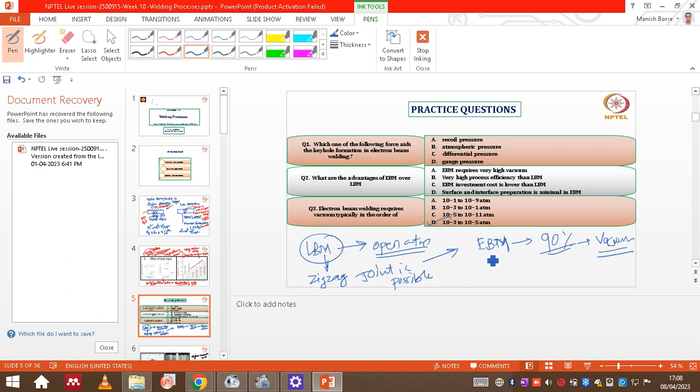But again, if we consider energy beam density, the power beam density is higher in the electron beam welding process, and because of that, we can ensure much deeper penetration than laser beam welding. We can say even a 15 to 20 centimeter plate can be joined in one single pass, right? If you remember, the professor taught this in the regular lectures, right? So